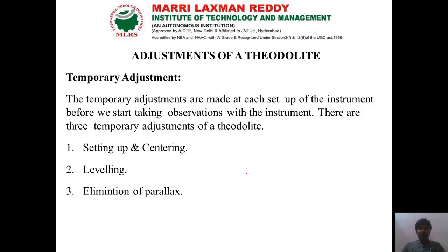Next, the adjustments of a theodolite. Whenever we go to the field, we should do some temporary adjustments. Only then will the instrument be ready for taking measurements. Those temporary adjustments are, first, setting up and centering. That is nothing but placing the instrument over the exact station point. That is called setting up.